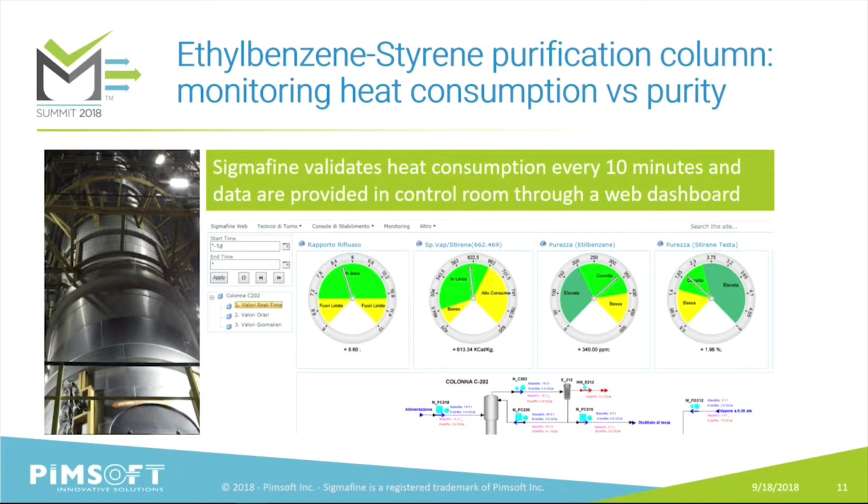We have in the thermal library all of the correlations needed, like Redlich-Kwong and Peng-Robinson equations of state. We do all of these mixing rules, and then we can compute energy on a reconciled basis and on a measured basis. That's another example of automation.